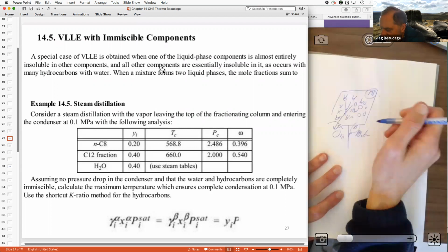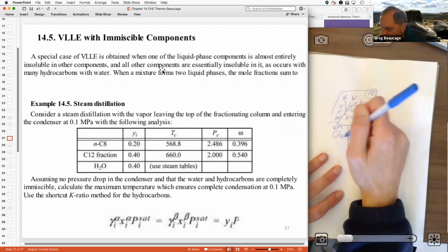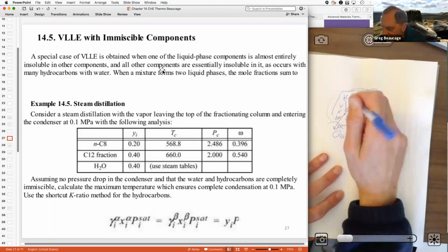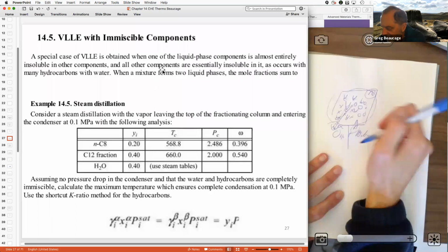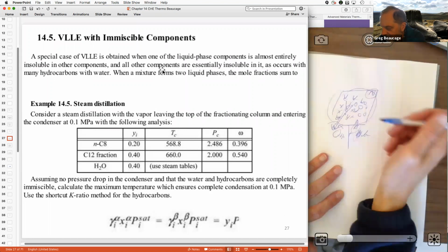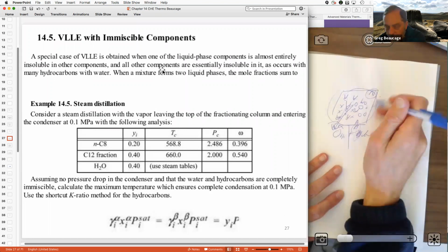So you shift the boiling point by putting in water, right? Water crowds up the vapor phase. That's going to push things back into the liquid phase. So by adding steam, you can lower the condensation temperature. The dew point will drop because of adding water in there.